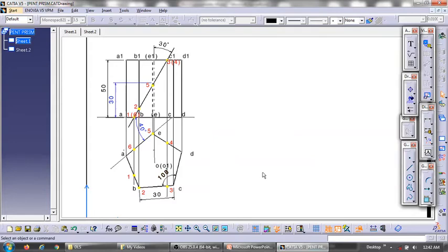So you have located these intersection points on the true length of the top face edges and base edges. Now all you need to do is find out the distance of these intersection points from one of the corners, either the top face corners or the base corners.